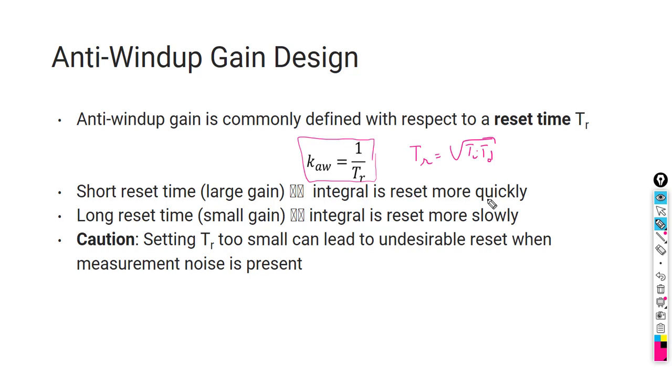It's exactly like a proportional action. If you have a long reset time, it means small gain, so the integral is reset more slowly. So it depends on you.